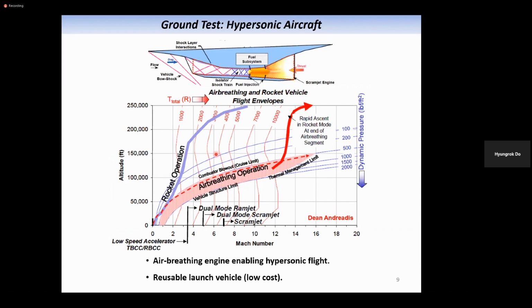And in this case, your measurement becomes more important because your flow is too fast, and to produce this fast flow at a decent temperature, you will have to heat up the gas in the upstream so high. So maybe some molecules will be dissociated and some molecules could be excited, and that will make some difference in your experiment. So optical measurement becomes more important, particularly for high-speed aircraft testing.